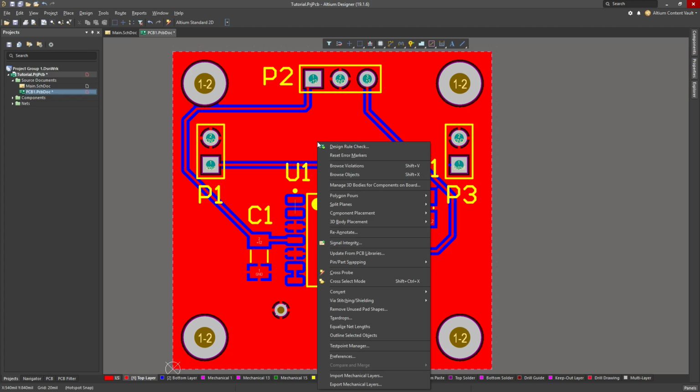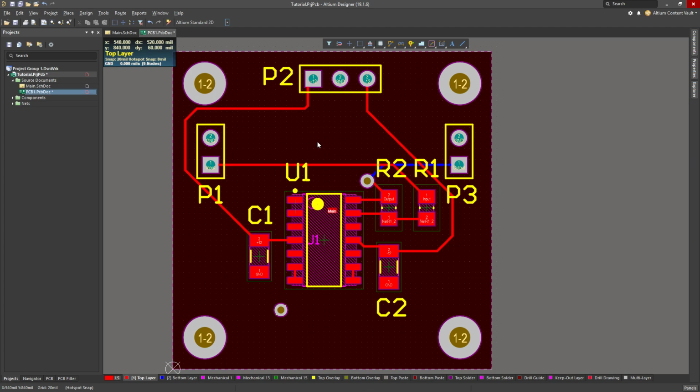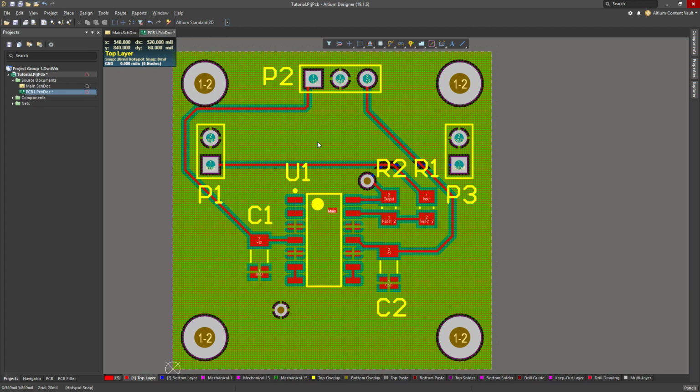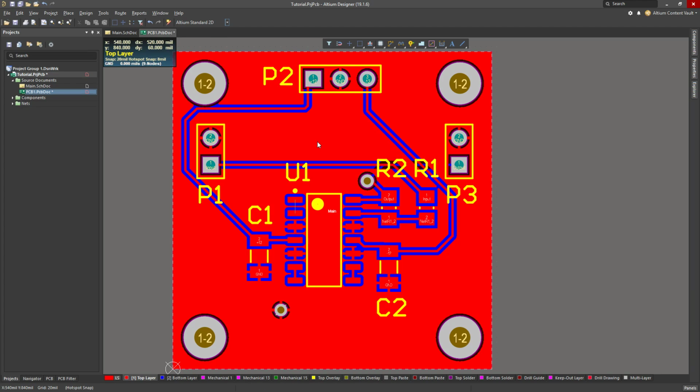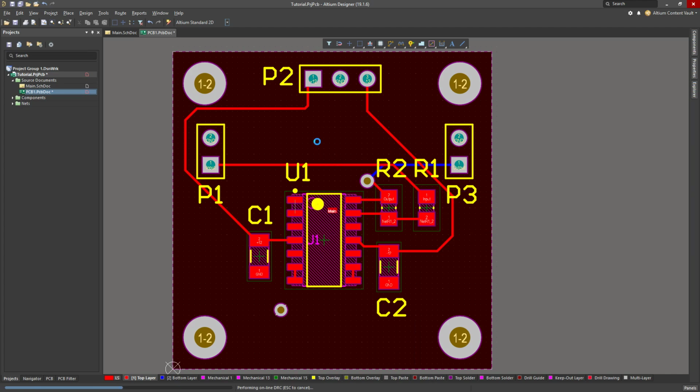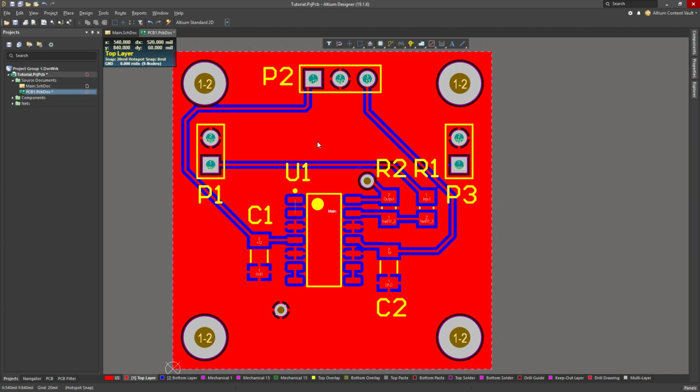And then again you see the underline, so G for polygon. And then again, if I want to shelve it, that's H. So that was TGH. And so TGE will restore, TGA for repouring. You find yourself using these keyboard shortcuts all the time, so it's useful to remember. So TGA to repour your polygons, for example.